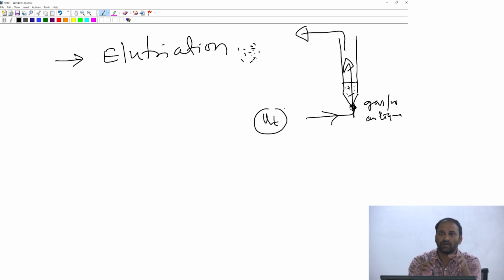So having an idea about the terminal velocity, also called the terminal settling velocity, because when you're talking about motion of a particle under the influence of gravity it's basically settling, is useful. Depending upon whether the particles are smaller or larger, and whether the Reynolds number is less than 1 or more than 1000, you should be able to come up with some estimate of the settling velocity of the particle. Once I have an idea about that, by regulating the flow rate, that is the velocity with which the fluid enters the column, I can separate particles into different fractions.